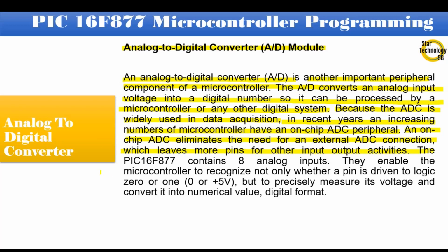The PIC16F877 contains 8 analog inputs. They enable the microcontroller to recognize not only whether a pin is driven to logic 0 or 1, 0 or positive 5 volts, but to precisely measure its voltage and convert it into a numerical value, digital format.